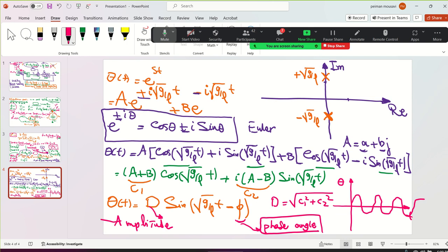So when you're oscillating, this is physics that you learn, hopefully. You have a frequency of the oscillation. What's that frequency? Here we go, natural frequency, omega n. You guys who have passed the vibration course with me know how we derive that, but if you didn't, I'm teaching you here. So this is the natural frequency of the system.